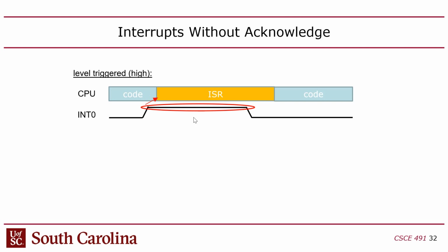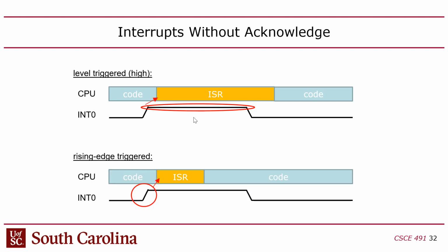They can be basically one way, where you've got a wire that goes from the peripheral to the CPU, and in that case, the interrupt could be configured to be level triggered, where the CPU responds to the interrupt being active high, or edge triggered, where the CPU responds to the rising edge or the falling edge. On the Arduino, the Atmel 328P, you can actually configure that in the hardware, whether you want it to be level sensitive or edge sensitive, and if edge sensitive, it can be rising or falling edge sensitive. You'd have to set that up according to what the peripheral is doing that you're connecting to your CPU.